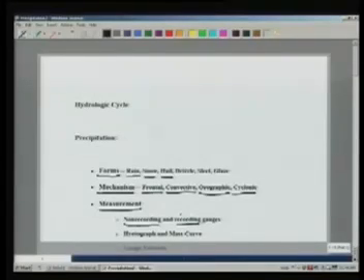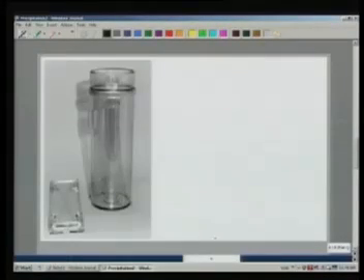In the non-recording rain gauge, this figure shows a typical non-recording rain gauge, in which on the top we have a funnel to carry the rainwater falling on it. This funnel then carries water into a graduated cylinder on which we can see the markings which tells how much rain has fallen in that period. Typically in India, around 8 or 8:30 a.m. a person goes and looks at this rain gauge and finds out how much rainfall has occurred in the previous day. So a fixed time every day somebody goes and watches the amount of rainfall.